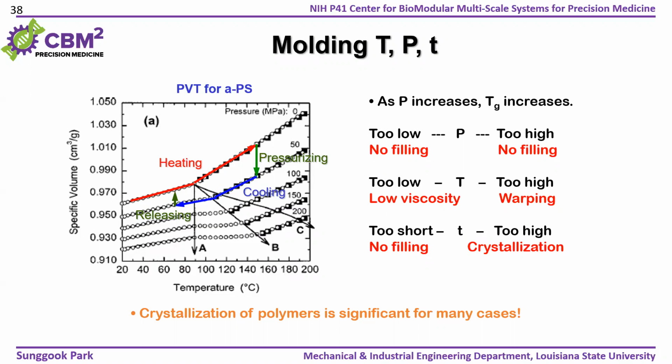The second one is thickness. Even though they report, oh, the thickness of our layer is this, you cannot trust it. Thickness can never be uniform. There's always a variation, and it also depends on the homogeneity of your film. You know what the third one is? Operators. This means you have to really work and determine the parameters for yourself. All the values from the literature can be a guide, but you have to really determine the process by yourself.